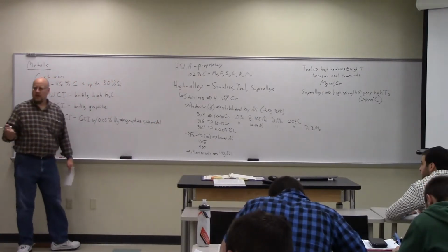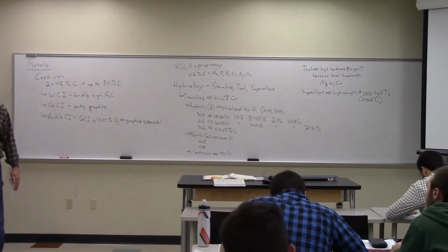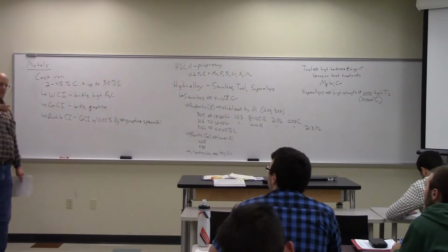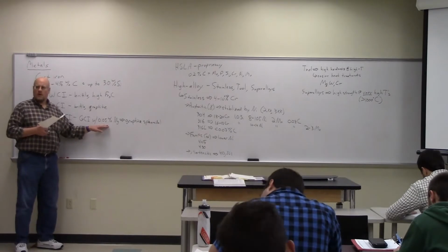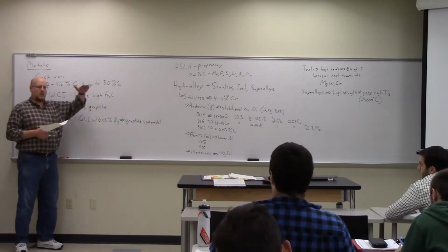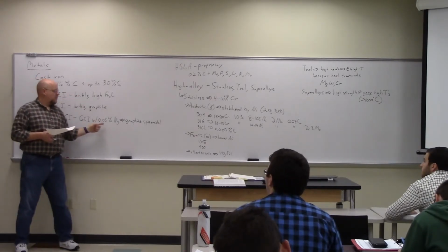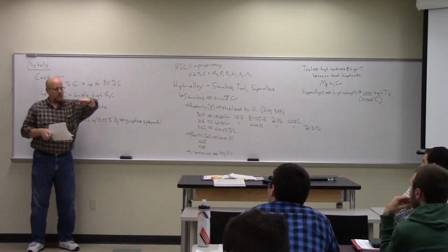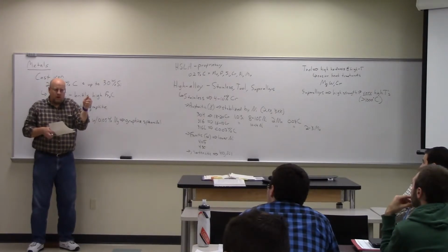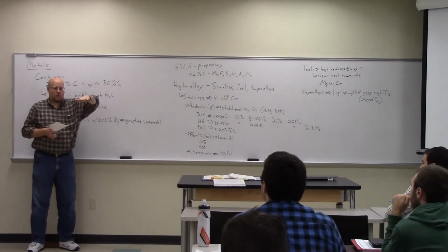So what does graphite want to be? Sheets. Sheets, right? That's the hexagonal structure, right? The plates of graphite. So if you have plates of graphite, it inhibits dislocation motion, right? Like we talked about with the bainite. You get these randomly oriented plates, it's a problem. But if I make the graphite spheroidal, that plate that would be blocking a whole bunch of dislocations from propagating now just became a sphere this small. Now the dislocations can propagate around. And a sphere is the least obtrusive obstacle. A plate is a much more obtrusive obstacle.